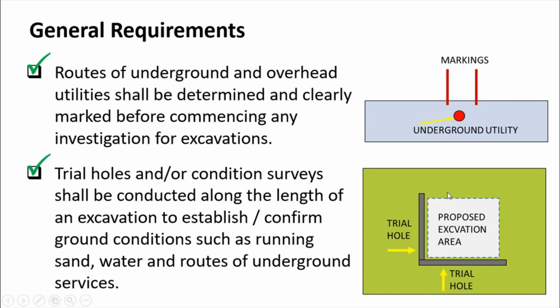If you are not sure whether the underground utilities are buried here, because sometimes the as-built is not truly reflected on the site, it is always better to make the trial hole. So this is the way we can do the trial hole before we allow the machine excavation.